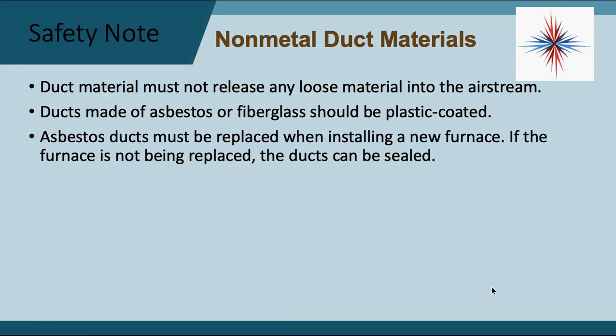Okay, so the minute you start replacing pieces of ductwork that are made of asbestos, it becomes an environmental cleanup. So if you have asbestos ductwork, if somebody cleans the ductwork with a brush, all of a sudden you have an asbestos problem. Asbestos ducts must be replaced when installing a new furnace. If the furnace is not being replaced, the ducts can be sealed. Again, asbestos ductwork, the best thing you can do for any customer is to replace those things. It's a bad idea.